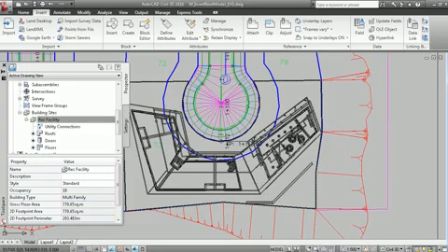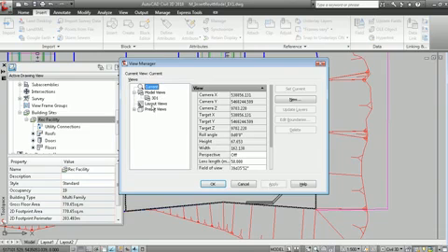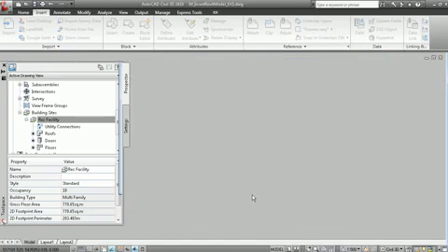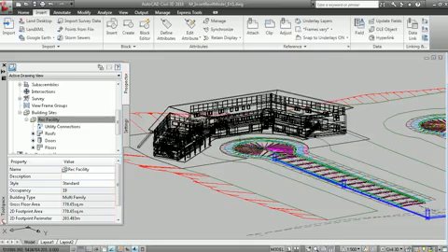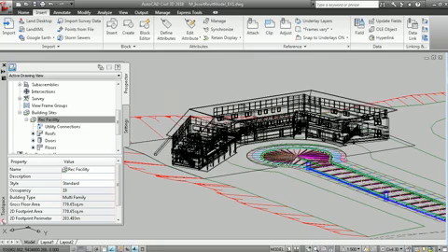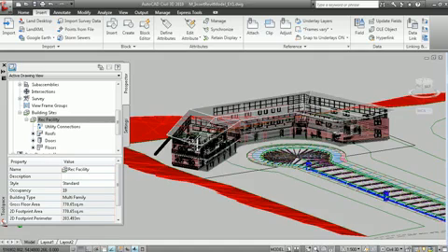And if you look at it in 3D, we have a 3D view saved. We can set that as current and click OK, and you will actually be able to visualize the building site in 3D. And you can shade or render. I'll just issue the shade command here to shade that site. But you can see the road cul-de-sac here, the pipe networks, the grading of the site, and also the building here. So once again, it's very useful to be able to show all of this data at the same time, both the above and the below ground data.